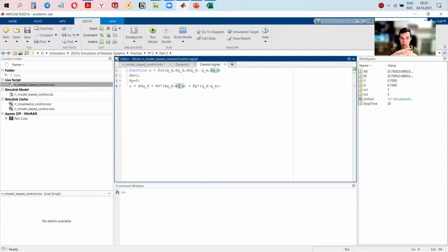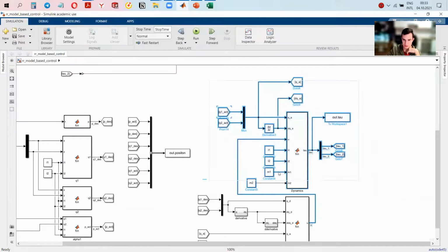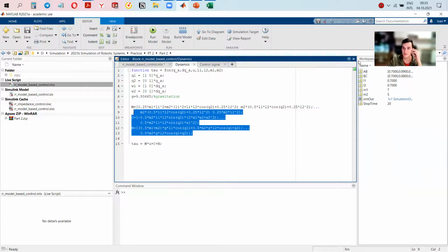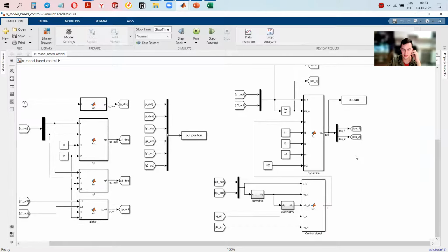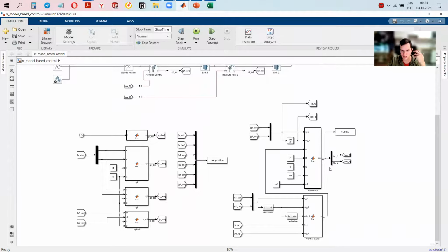we use the model, we can see now that our coefficients of control, proportional and velocity for the damping, are pretty much low. It's all because of the model, because now our control is effective: it knows how much energy we need to steer the system, because it knows about the mass distribution. It knows how much force it needs.